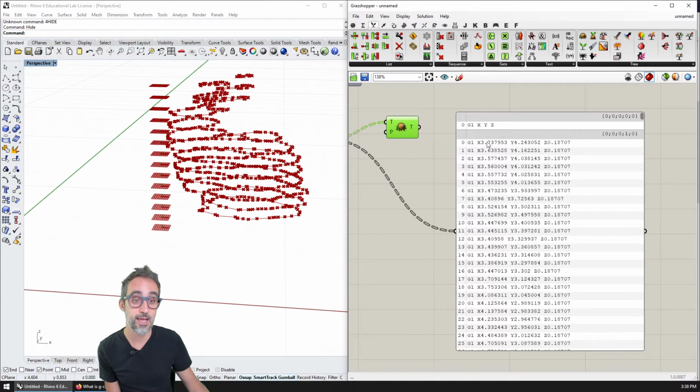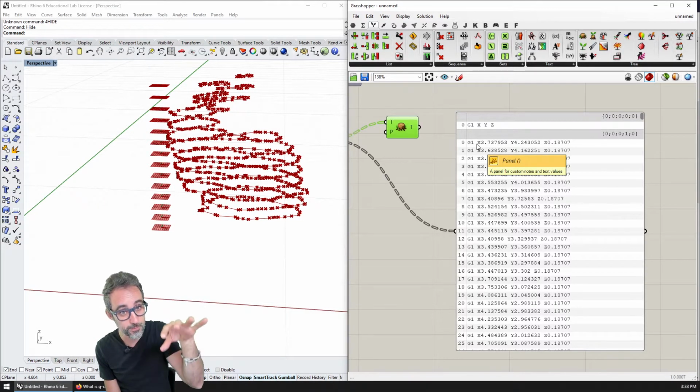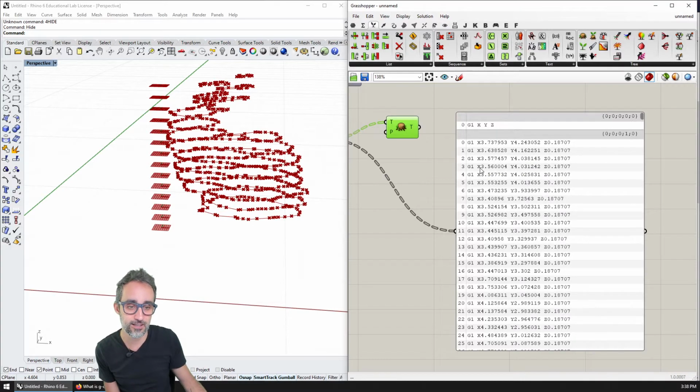operations such as at the beginning of a contour, we need to approach the contour from above, and then we need to lower down. So at the beginning of the contour, we will need to move the pen down, turn on extrusion, and then start extruding all the way in.